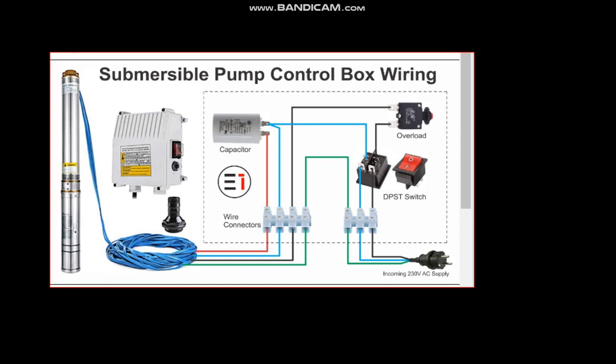Okay. So let's design a circuit to control the small pump by adding a flow switch. Okay. So let's start by bringing our supply. This is our supply. Then we also have a breaker to protect the pump from overload and from a short circuit. After that, we have a switch here. After the switch, I have overload. This is my overload. Okay.